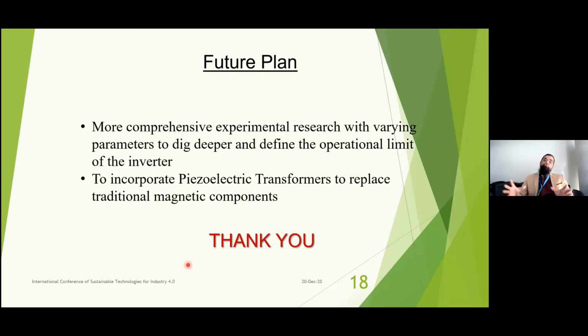And also we want to incorporate the piezoelectric transformer to replace the magnetic components. Because PET is a very small device, if you can change the magnetic components, you can change the resonant tank with a piezoelectric transformer. So basically, we can reduce the size of the total circuit.